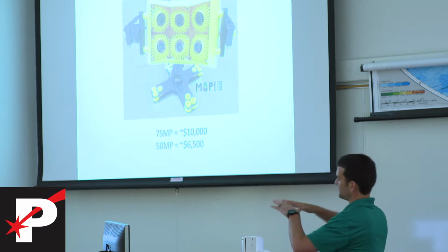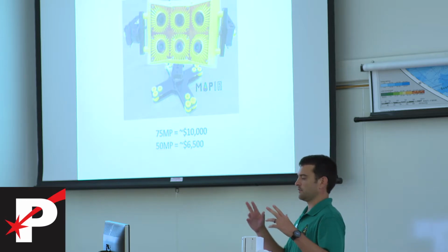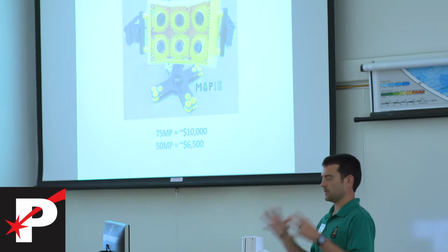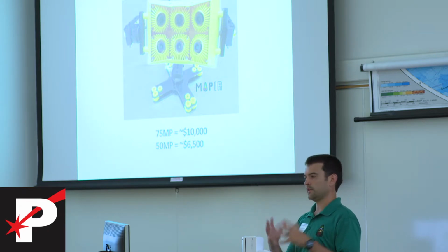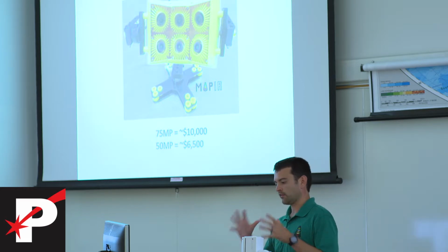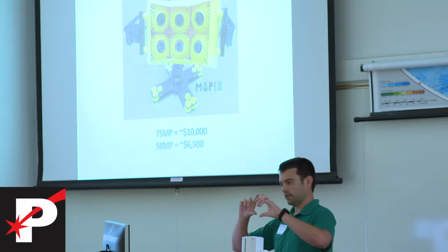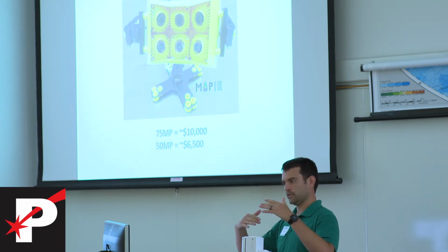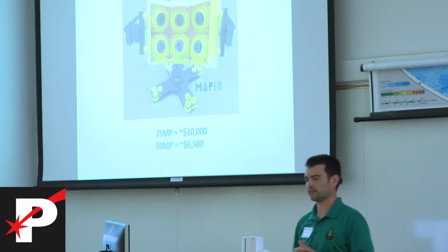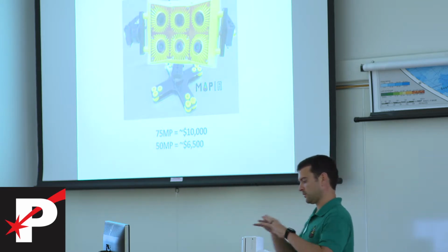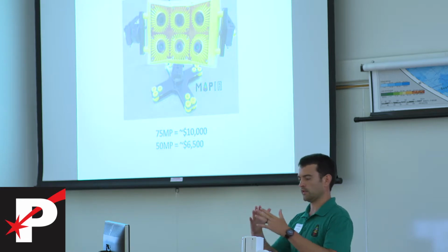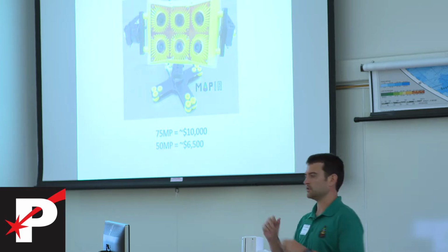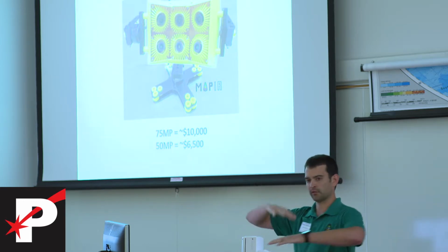And the ability of this, because it is curved, if you think of the field of view of all the lenses, they all go to a common aperture, a common point in space. Once you calibrate the camera array, it becomes a camera. So you've taken 6 cameras and you form a camera. That single camera can now shoot a high resolution image that also has 3D depth to it, like photogrammetry, like you saw with the DroneDeploy stuff, and it also is measurable. Once you completely characterize a curved camera array, and you know the exact orientation of the sensors and everything, you can take a single shot and you can measure it. You don't need to do a full photogrammetry, multiple sensor array kind of situation.